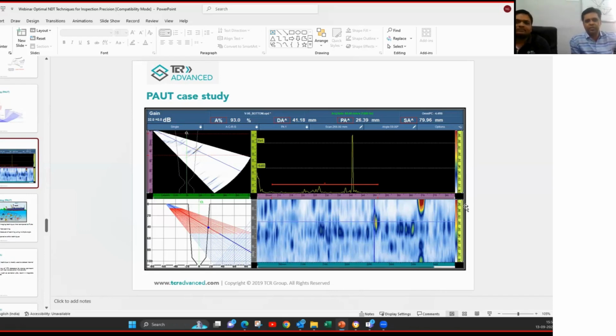Visual inspection is non-intrusive. We find anything on the outer surface. If everything is okay, it's fine, and we can continue using it. The next thing is that you check the thickness measurement. It is also kind of non-intrusive because we can check it from outside only. But that is possible only on the shell and the roof portion, and that can give us a fairly good idea.